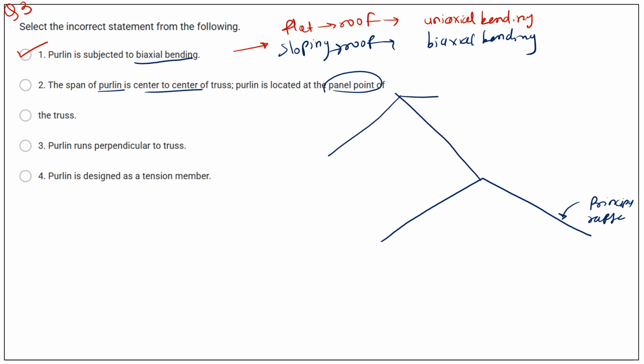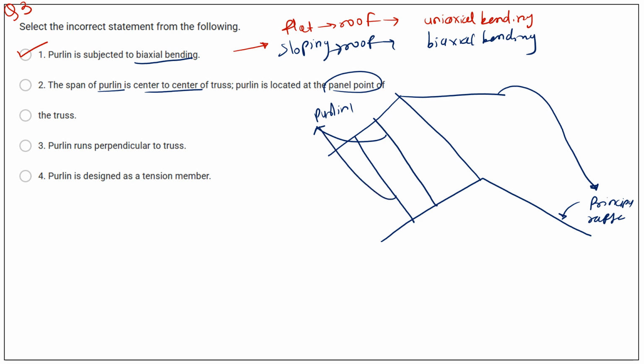And here at the last there is also the principal rafter. On the principal rafter we place the purlin. Here. Okay, so this is how the purlin is placed, and to support the purlin, cleats are provided here. And in the remaining part here, common rafters are present.